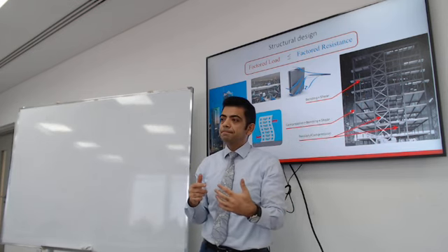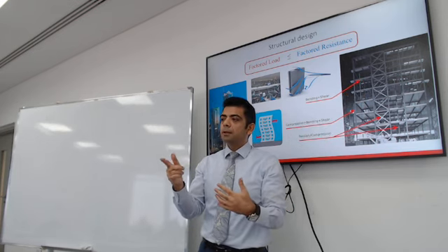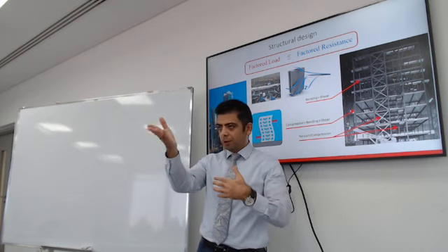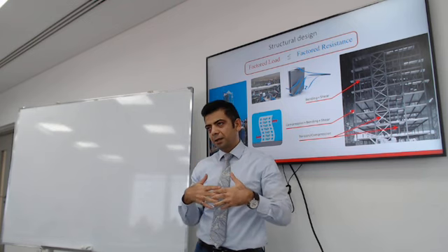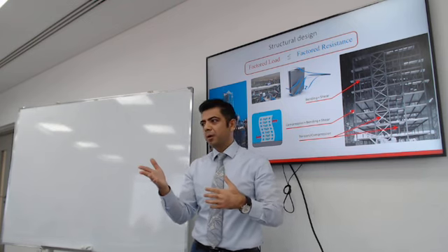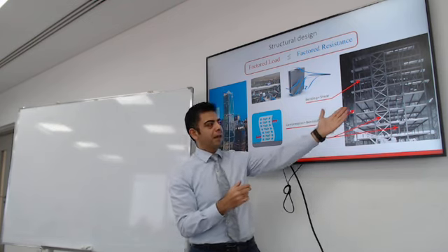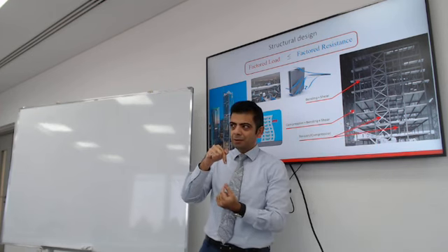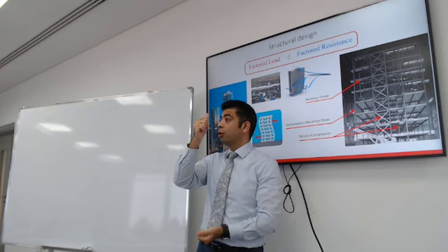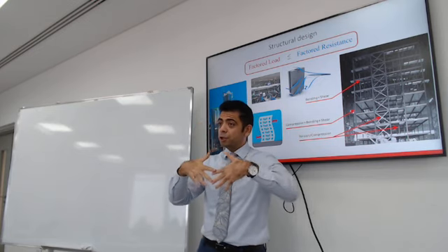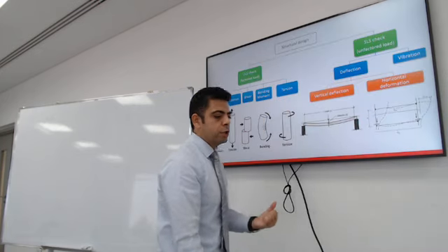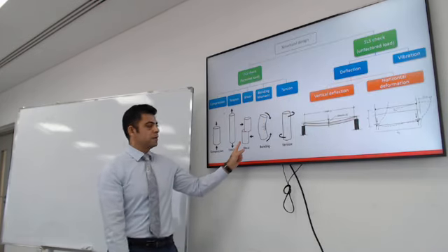Load of the slab. Yes. What are these loads going to create on the beam? They're going to create shear and bending. That's right. That's what I'm talking about. So you look at the element that you're trying to design and figure out the internal forces. Is it axial load? You design for compression or tension. Is it bending or shear? You design for bending and shear.